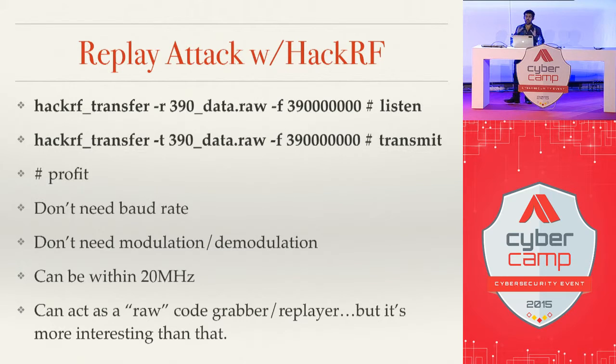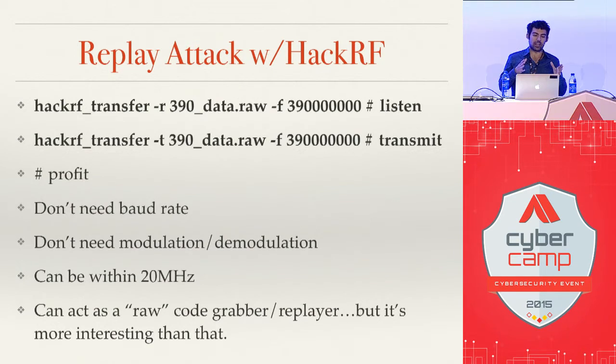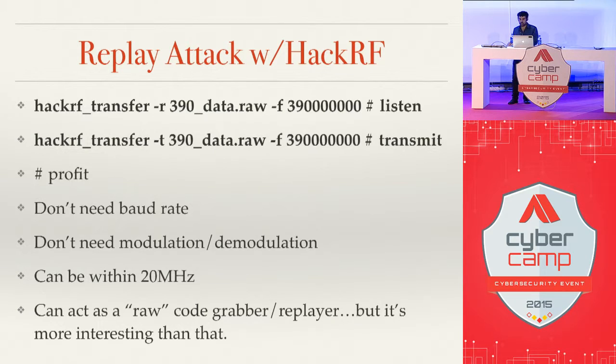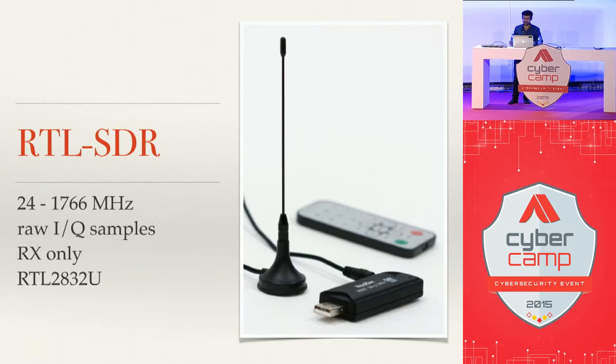It can listen to 20 megahertz at a time. So you just have to be within 20 megahertz to actually capture the data. So if you see someone hitting a garage door button and opening a garage door, and you capture it within 20 megahertz, then you can replay that to open that garage door, assuming it's using fixed codes. So this is pretty cool, but we can do a lot more advanced things.